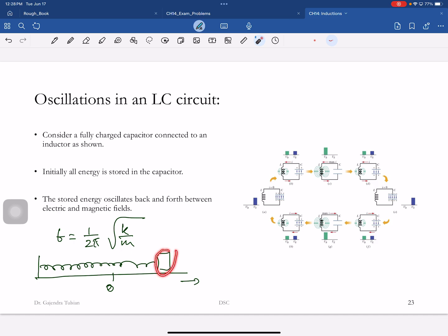This has spring potential energy and kinetic energy. Whenever a system is oscillating, all that is happening is energy is being converted from one form to another. You can have more than two different forms of energy and you can oscillate too, but that's what's needed. So for a system to oscillate, it has to be able to have energy in two different forms, and when it's oscillating, it's converting energy from one form to another.